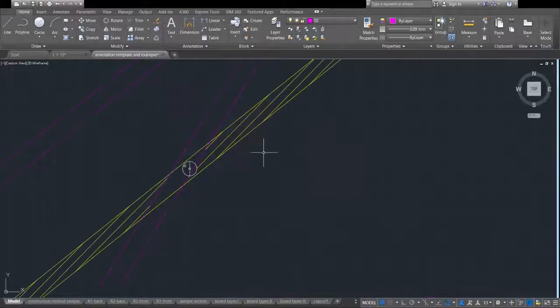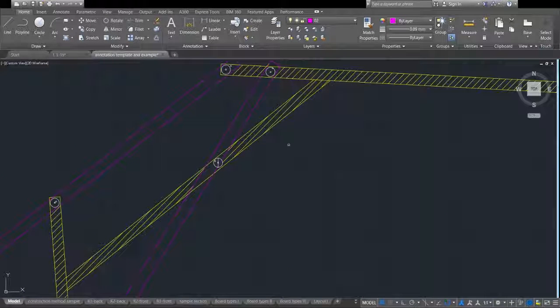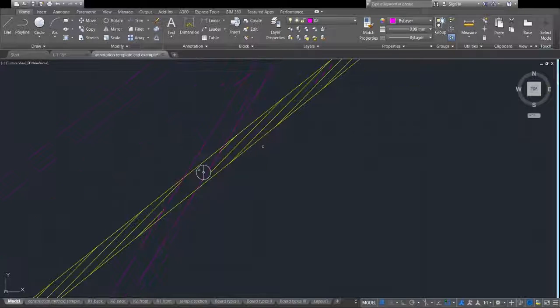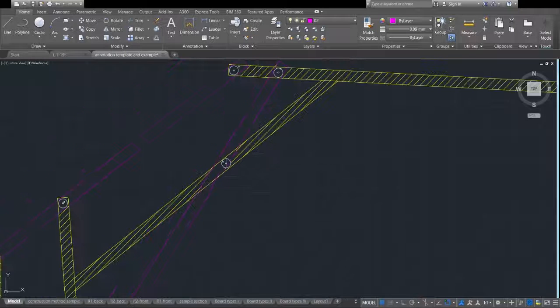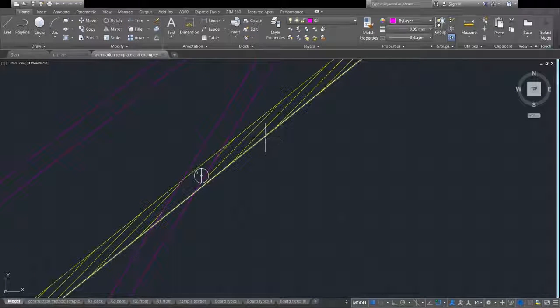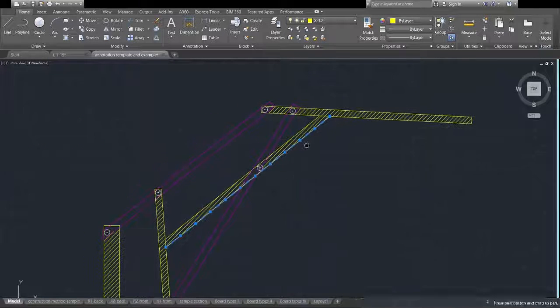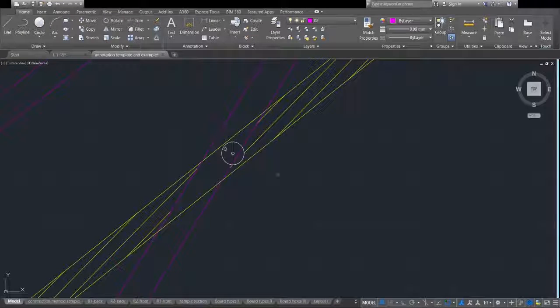All right. So one issue that you'll run into is that sometimes when you try and do a dimension angle on a piece, it's not going to like it. And there are two ways to fix this. One of them is you select a piece and you use the pedit command, and you just hit enter a few times, and then it's sort of fixed.